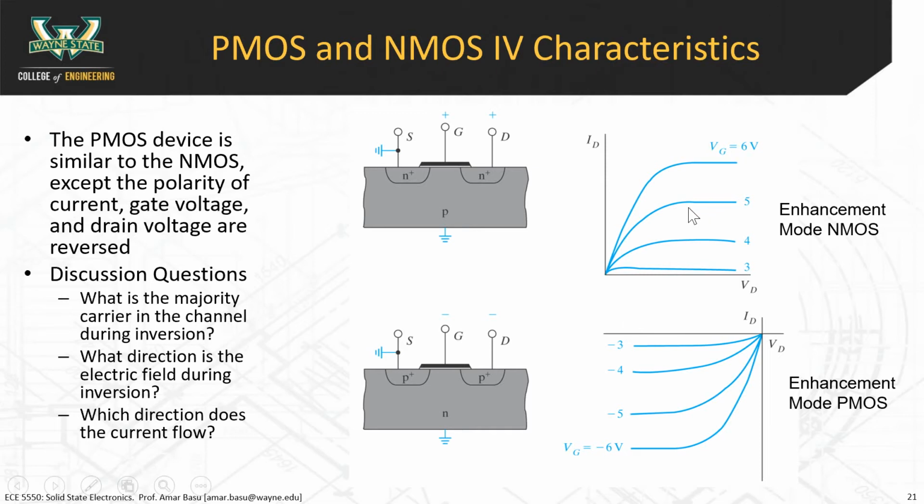All right. So at that point, there's a phenomenon called pinch-off that prevents the current from increasing much with any change in VD. So here it's behaving in the saturation region as a current source. A current source always delivers a constant current regardless of the voltage. At low values of VD, when it's in the triode region, it's actually behaving as a resistor, where my mouse is right here. And in the middle, the transition region, that's where the IV characteristic is nonlinear. It behaves almost like a quadratic function, has a quadratic element to it, and that is the top end of the triode region.